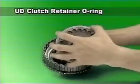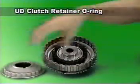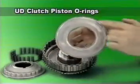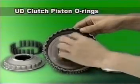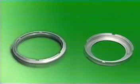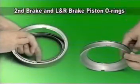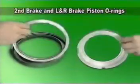Next, check the 3 O-rings placed in the underdrive clutch. If these 3 are damaged, trouble in driving forward and transfer shock may occur. This is due to oil leakage of the underdrive clutch. Next, check the inner and outer seal rings installed at the piston of the second brake and low and reverse brake to identify any damage.